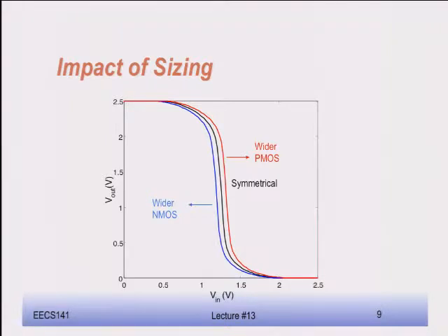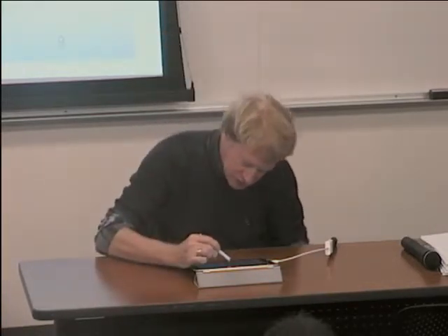The other thing to remember, I already mentioned that, but if you look at your voltage transfer characteristic, this is a beautiful inverter, very nicely sized. You can see that for the black curve, the nominal curve, my midpoint is exactly 1.25 volt, purely symmetrical. Now remember what I said about changing the transistor ratios? If I make my PMOS wider, what happens? VM goes up, right? PMOS wider, the resistance of the PMOS gets lower, it pulls up the VM. And you can see that happen right here.